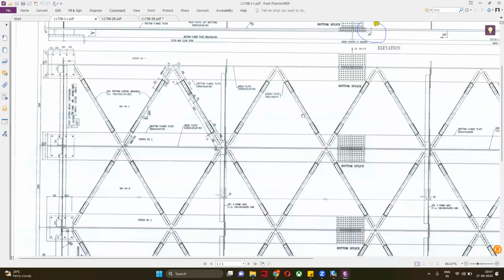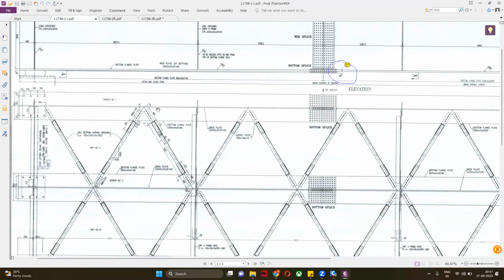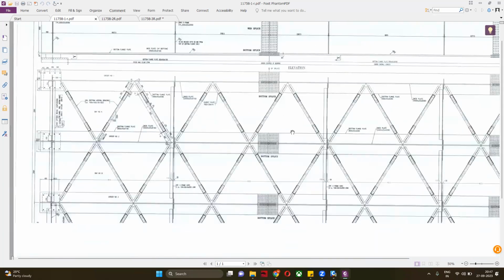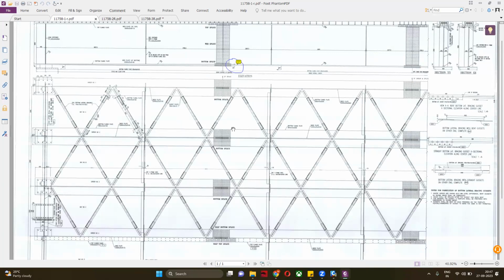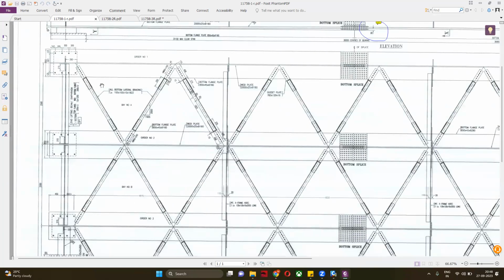Is it mentioned anywhere, or are we assuming this one, sir? No, it should be equal distance. So what I have done, I have calculated, it is giving me around 1.525. So I'm considering 1.5, and the remaining one will automatically be considered, because there are no issues with the bracing. I'm just following the drawing; you can even adjust according to your own, you can provide equal bracing. I'm using this one so I do not want to conflict with this drawing. Otherwise, is each spacing 1.5, sir? Not each. This is 3 meter, and from this to this is 1.5. So this to this is 3 meter, how did you calculate, sir? Yeah, this 3 meter, first 3 meter.